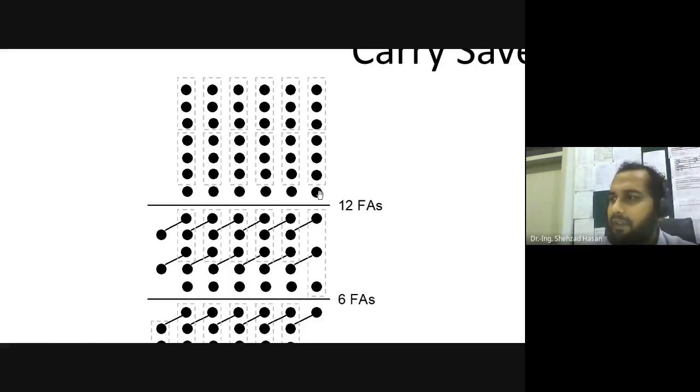Yeah, and the third one over here, it's just copied over here. Okay, so these 7 bits have reduced to just 3 bits. Okay, let's go for the next level. In the next level, do the same thing over here. So 3 bits getting one bit at this level and 1 bit at another level. These 3 bits getting 1 bit at this level, and this copied together over here. And you're getting 2 bits from the previous level. So in total, you have got 5. So what you have done is reduce those 7 numbers into 5 bits over here. Okay, that you have to add finally, right?